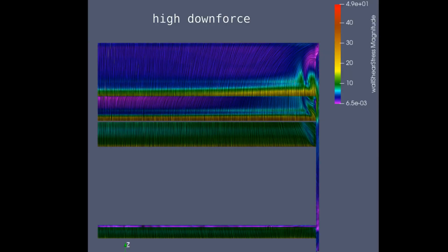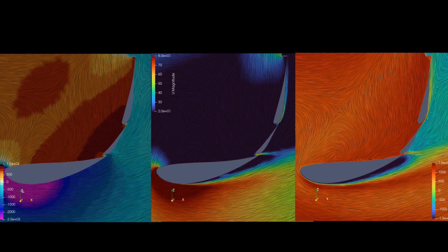The same process was followed for the high downforce wing. Run it in the simulations by itself and add it to the car later. This wing by itself gave 1458 newtons at 422 newtons of drag. I was happy to get within 10% of the stated 1600 newtons from the paper. Then I placed it on the car, and negative 1070 newtons.